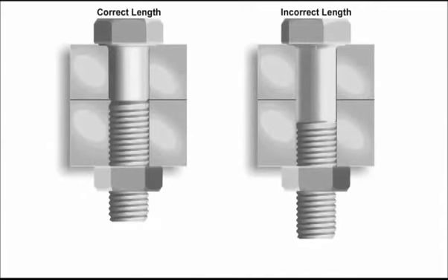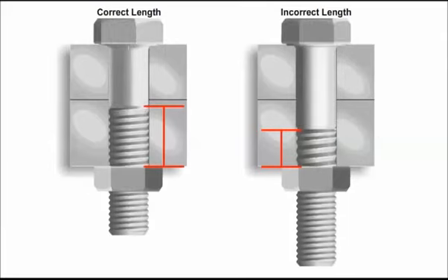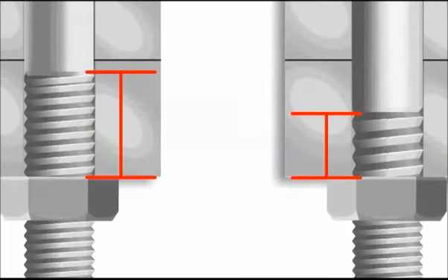If too long a fastener is used, there may be enough thread to tighten it to the listed specification. However, the area where the majority of the fastener stretch takes place is dramatically smaller. For example, if we torque each bolt shown to the same specification, we stretch each bolt the same amount. But the longer bolt has less unengaged threads available to stretch. Therefore, each thread must stretch a greater amount. This applies more stress per thread to the fastener, which may shorten its service life.